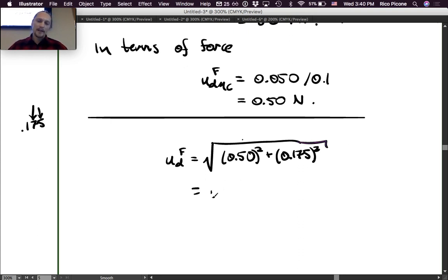And we'll get, according to my calculations, 0.53. So 95% confidence in that value for the uncertainty, which assumes 95% because no probabilities were given in the instrument specs. So that is the design stage uncertainty.